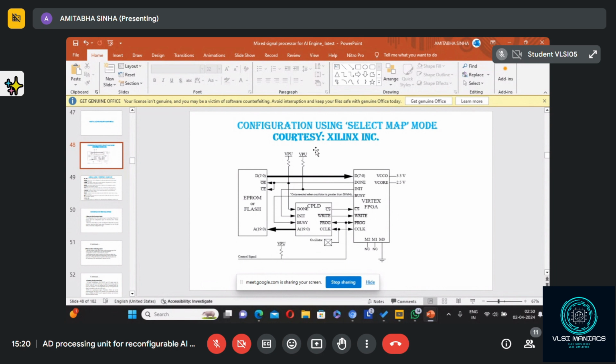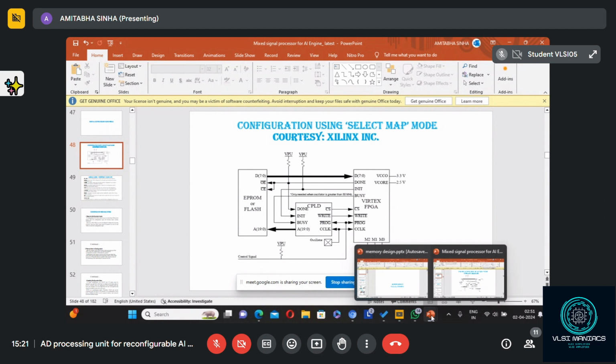The CPU will get interrupted by the CPLD, and once it gets the interrupt, it will understand that the bit streams have been downloaded. That means the FPGA will start behaving like a FIR filter. Once the task of the FIR filter is over, then if it needs to be configured as an IIR filter, the bit stream for the IIR filter will be downloaded and the FPGA will behave like an IIR filter. So do you understand the concept now? Yes, sir. Does anybody have any question?